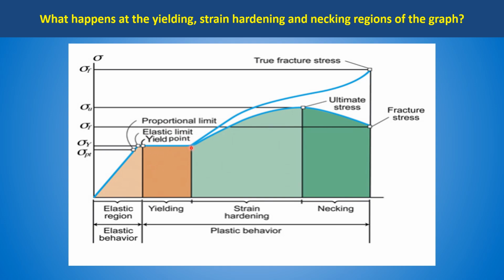And then we have strain hardening. This is where the plastic deformation increases a material's resistance to further deformation. It occurs due to the material undergoing changes in its atomic and crystalline structure. This is where the grains in metal dislocate and slip, paradoxically increasing the resistance to further strain.